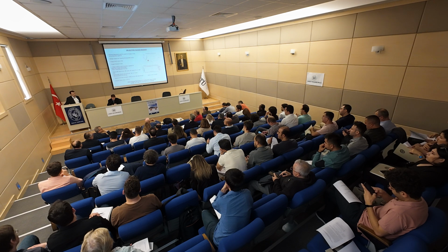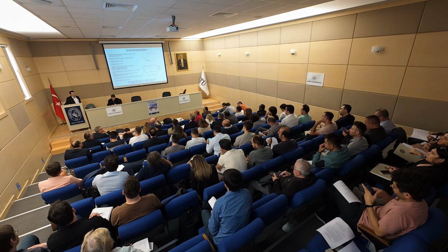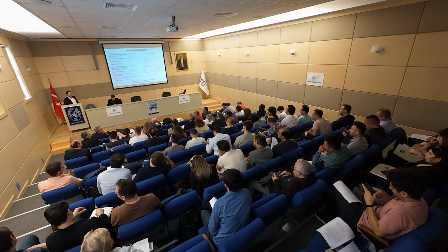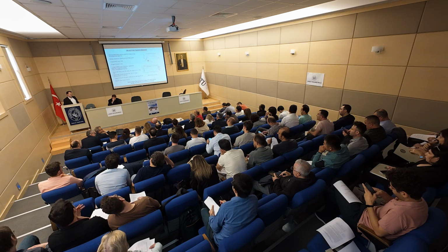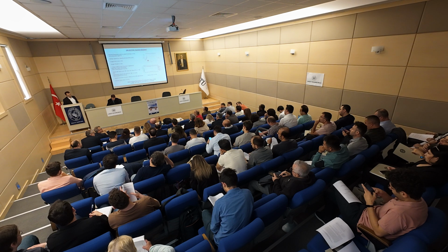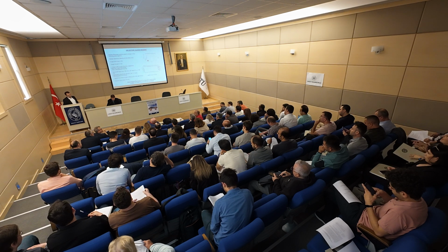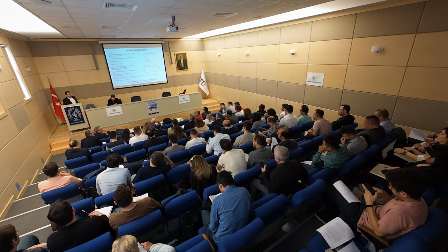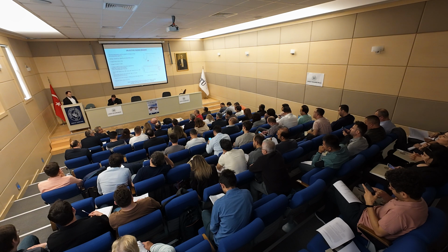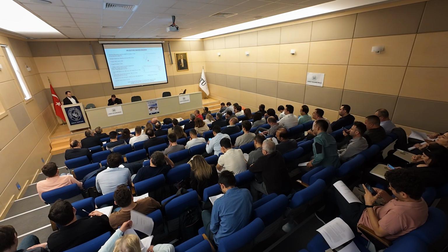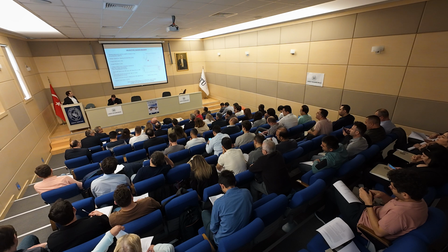That's where engineering intuition will never be replaced by, what do you call it, AI, artificial intelligence. Artificial intelligence would say that was good. As a designer, I would not make my diaphragm span the whole length of the building. Instead of using frames at the ends, I would distribute them, putting some in the middle to reduce the load on the diaphragm. I'm sure artificial intelligence would tell you that, but not this section.